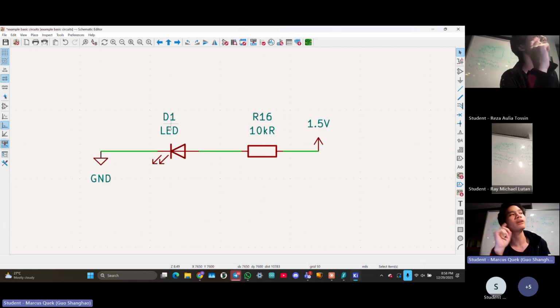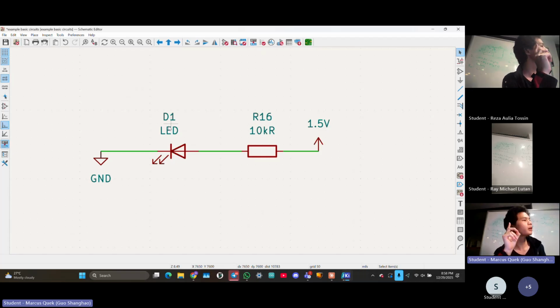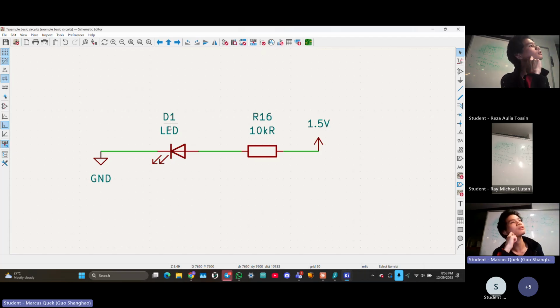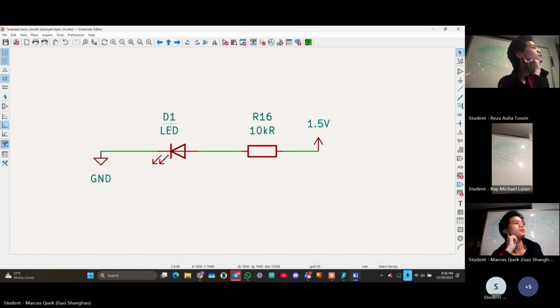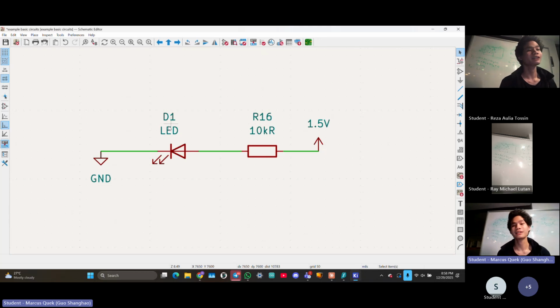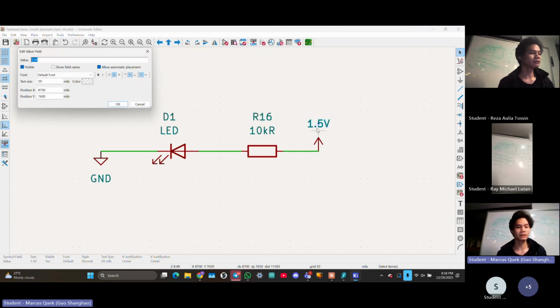Which means that I cannot run it on a single AA, right? Basically, a diode has a fixed forward voltage. So I'm wrong. Yes, correct. So then that means that we have to drive the thing with like 2 or 3 AA batteries in series. I have to achieve the forward voltage. I don't know what my LED is. Well, some LEDs are different. Oh, wait, yeah. Right. Okay. So I'm gonna change this to 3 volts.